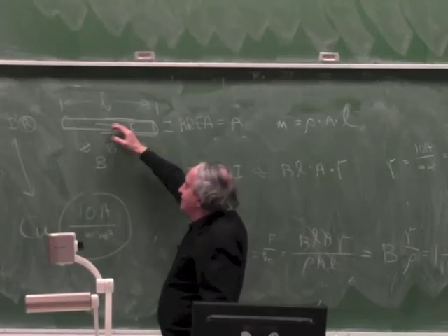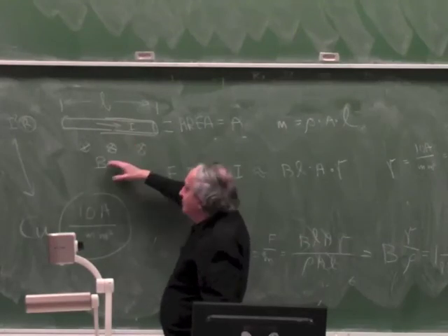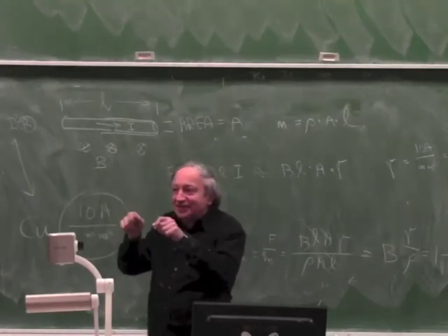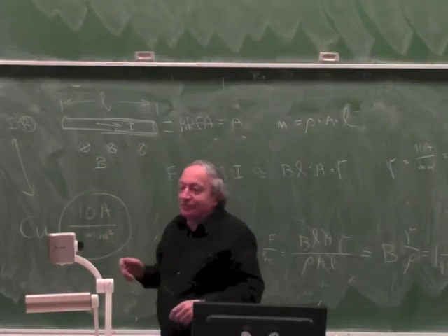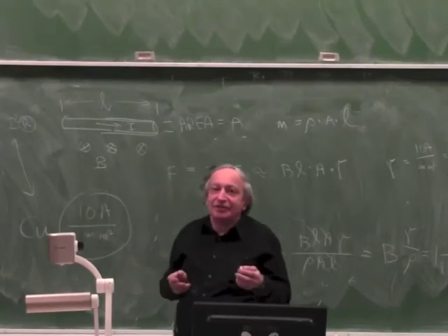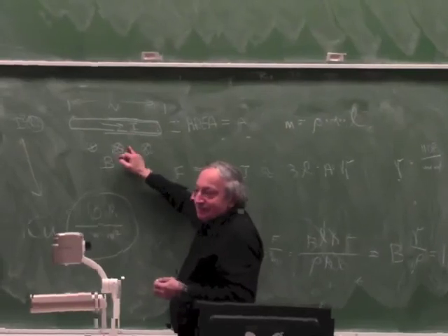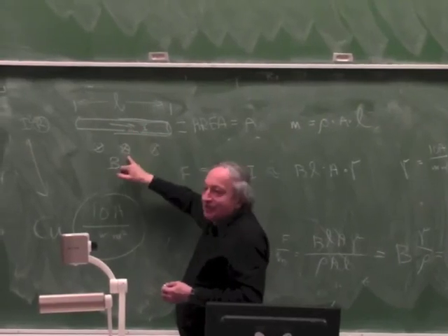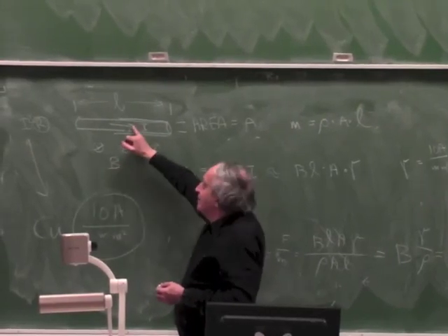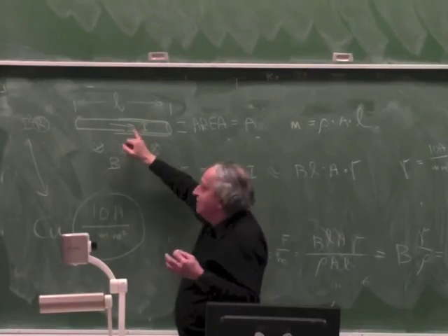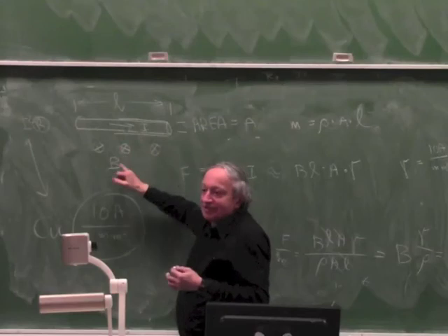The magnetic field this current creates interacts with this magnetic field just like you held 2 magnets together. And the force I get, the way the current interacts with magnetic field, is like the force between 2 magnets. The magnet caused by that and the permanent magnet. But if this magnet the wire creates is enormous, it will demagnetize the permanent magnet.